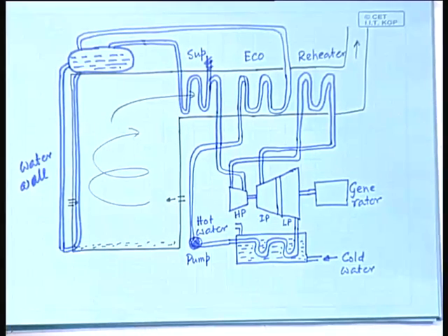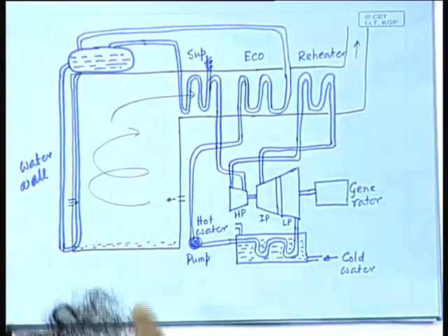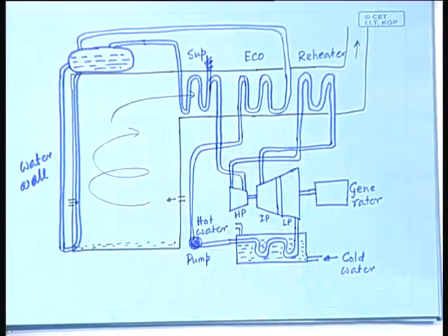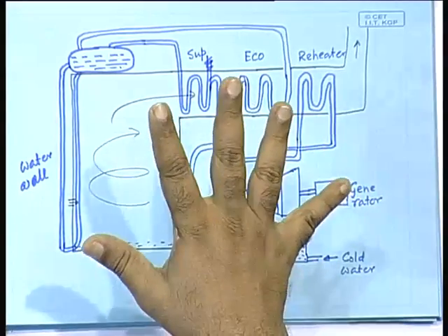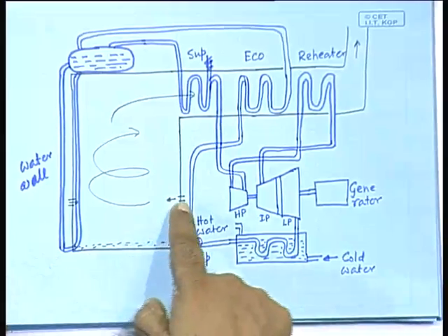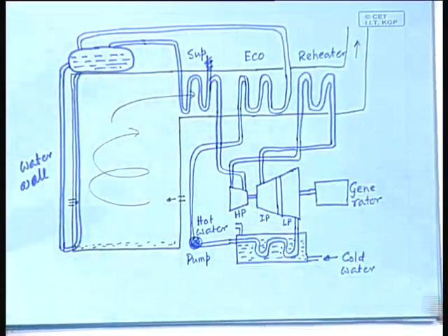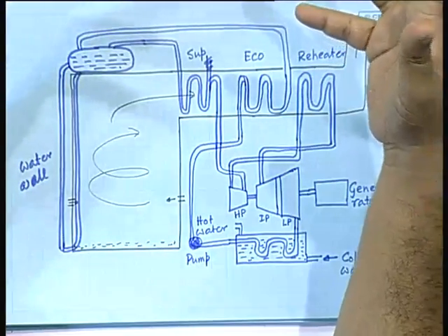So, what are the sources of loss here? Obviously, that is what energy engineers are concerned about, something that you want to reduce. One thing I should mention here: the reason the power station also consumes oil is that when coal powder and air are put into this, it does not fire by itself. It has to be put on top of a fire so that it ignites. So, initially an oil and air mixture is used, the oil is atomized.